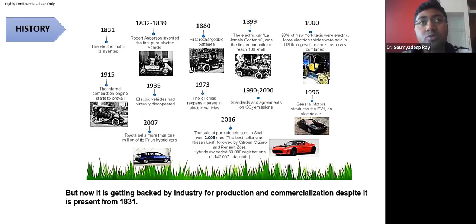Suppose 1C is 40 ampere, meaning the battery is able to take 40 ampere of current whenever it is charging by any medium, be it a fast charger or a slow charger. If the battery is rated 40 ampere itself, then it is called 1C.